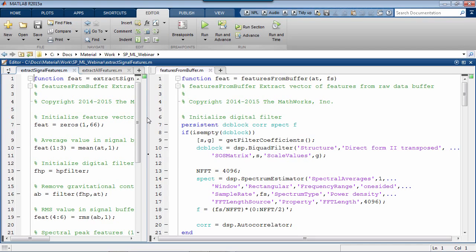Look, for example, at how we filter our signals. My first consideration really is just a side note, but it may help us get into the right mindset. Here we compute the filter coefficients for every new signal portion, even if they are always the same. We take in the full sequence of interest at once, and we assume to be operating on a pretty long one. As we do that, every time we assume to start with a filter with clean history, or zero internal states.